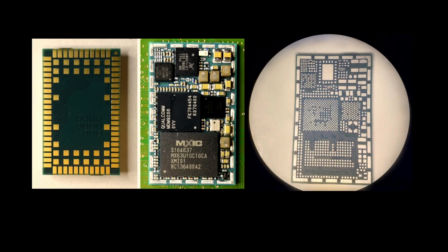And what we did in this case here, we literally threw the board in an oven, heated it up, and I took a brush and just wiped all the components off of it. Stripped it down to the bare board and start tracing everything out that way, using data sheets to map out all the circuits on the board.